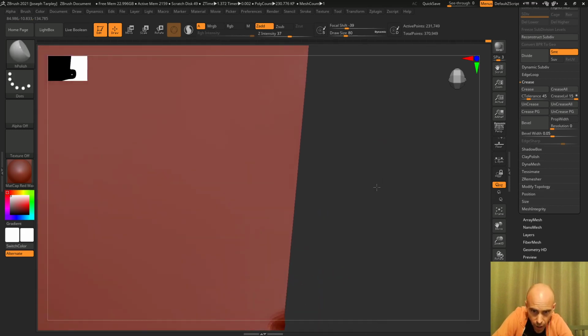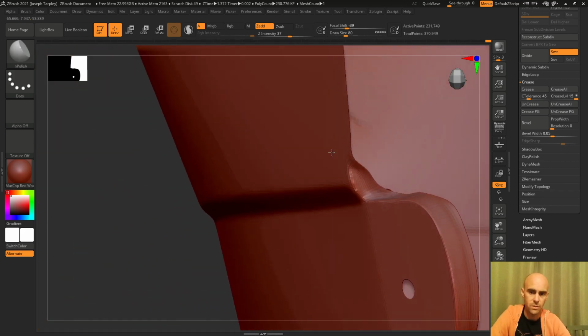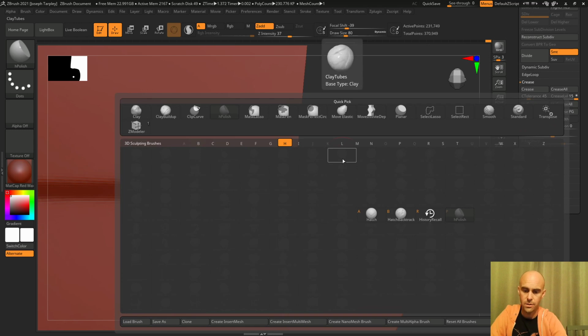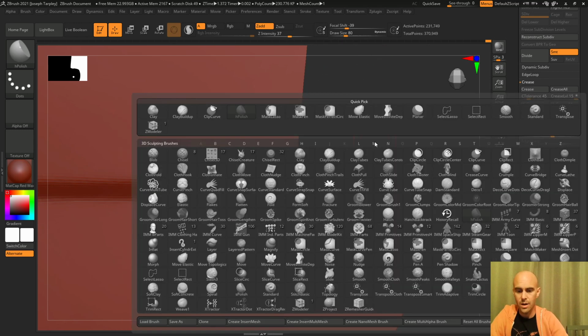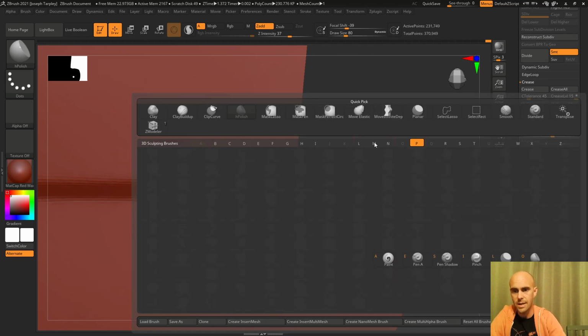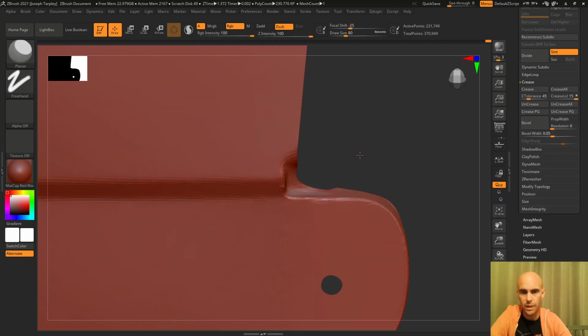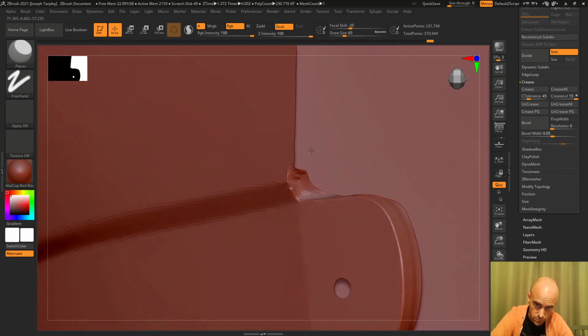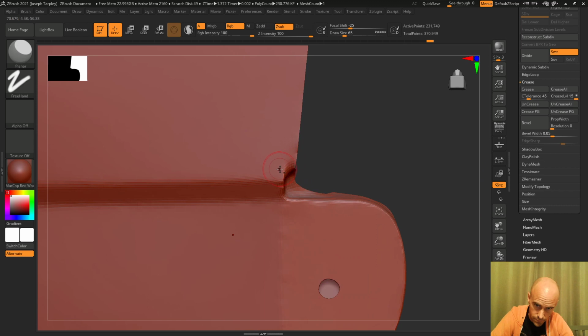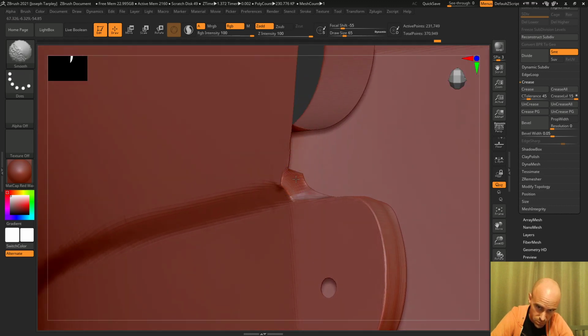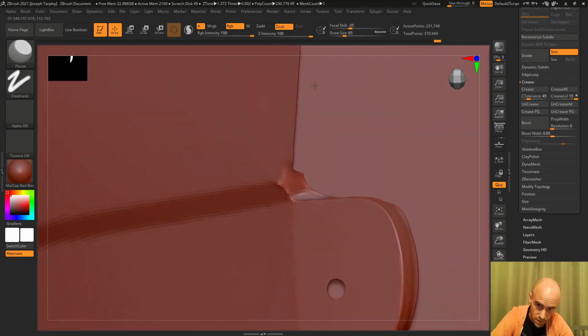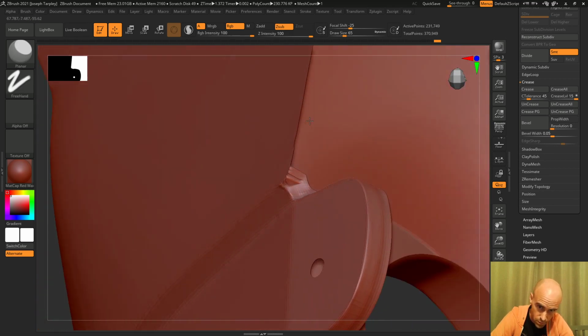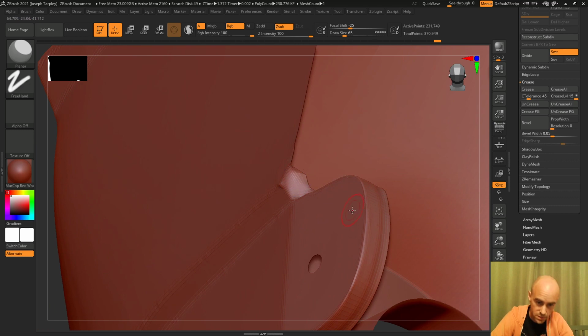And then at the very bottom, got this little weirdness going on. So we're going to do the same. We're going to go to BPL, which is the planer tool. I'm going to come in here and bring this out to the edge. It's basically taking that angle and just moving it out as much as possible. Sometimes you have to manually pull some polygons a little closer so that it'll work.